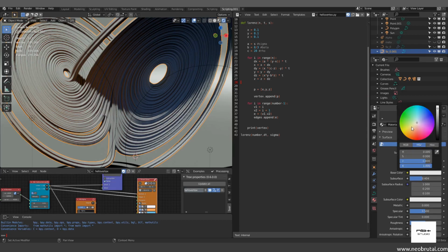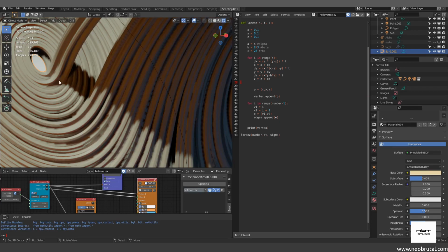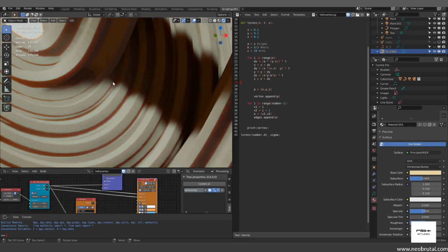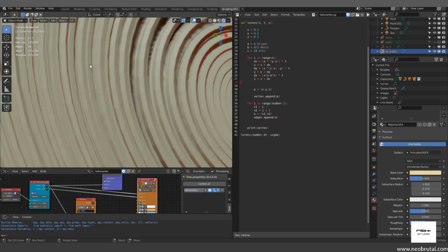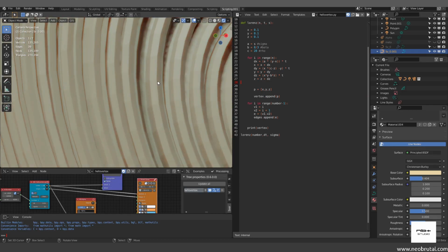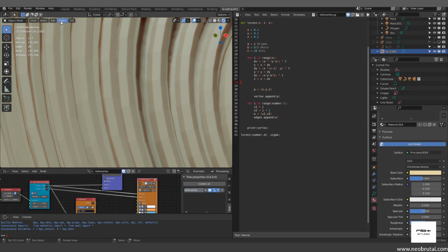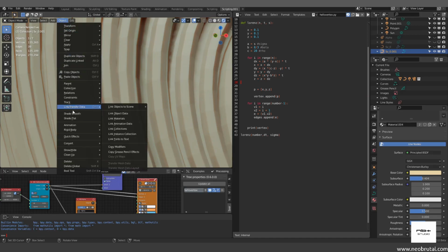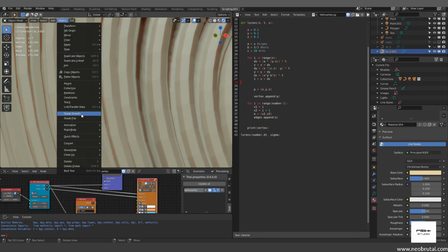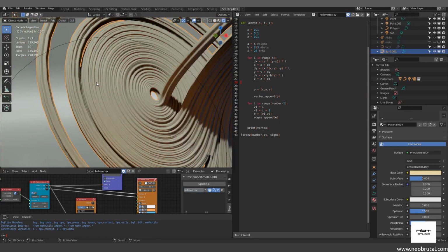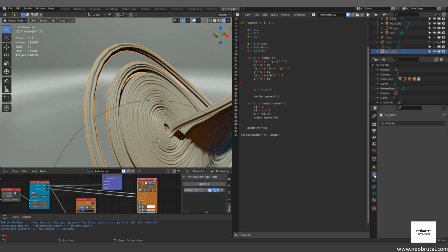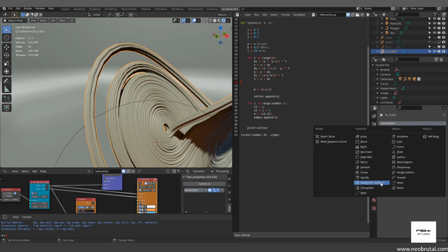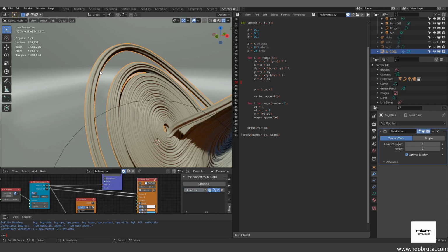And let's make it a little bit yellowish. So you can make it look like this kind of bone, ceramic look that you can give it. Now, as you can see, sometimes you get these lines, right? So to get rid of that, go to Object and click on Shade Smooth. If it's still a little bumpy, like here, you can actually see how it's bumpy, you can go and add a subdivision surface, and that should repair it.